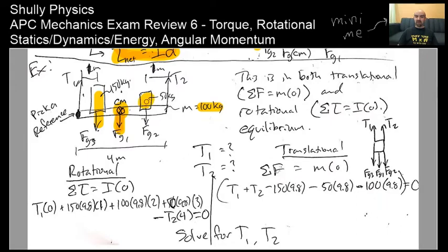And let's say there's a bucket of something that's 50 kilograms over here, so there's a weight of that, a weight of the beam, and a weight of the person, whose 150 kilograms of mass translates into a weight there. If we want to know what the tensions in the cables supporting the beam are, that would be tension 1 and tension 2. So what do you do first after your force diagram? Well, just make sure you consider what the R's are and what the angle thetas are. So here, each of our R's is going to be along this beam, so all of the forces are at an angle of 90 degrees. So we can cut out the angle, don't worry about that. Sine of 90 is 1.